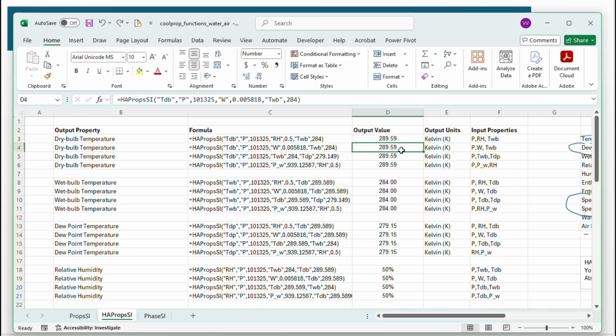And here you can see you're changing the inputs. Instead of the humidity, now you change this to humidity ratio, which is a ratio value. In this particular case, it's the kilograms per kilograms of moisture over dry air. So you could use those two inputs to calculate the corresponding dry bulb temperature.